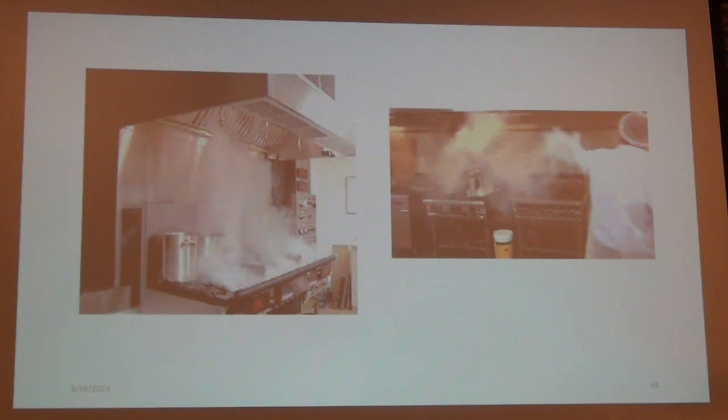Or they're not using, whatchamacallit, side curtains. Yeah. It rolls out and it's blown back. They go, oh, it's blown back. But usually when that blows like that, some of it still stagnates there, and not all of it gets sent back. But rarely do I have systems that fail anymore, especially with captive air. Those systems work great. If I have any smoke that rolls out of that hood and that PSP pushes it back, it's a fail. Yeah, that's your interpretation. If that's what you feel, it's the only thing consistent.